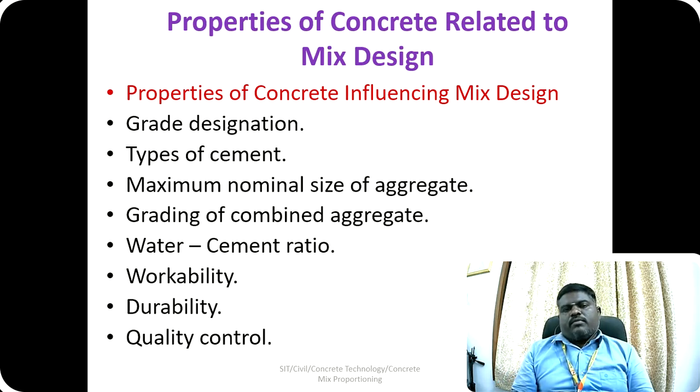Then the second point is the properties of concrete influencing design. The mix design is generally influenced by the properties of concrete. What are these properties? One is grade designation, the type of cement, maximum nominal size of aggregates, grading of combined aggregate, water cement ratio, workability, durability, and quality control.